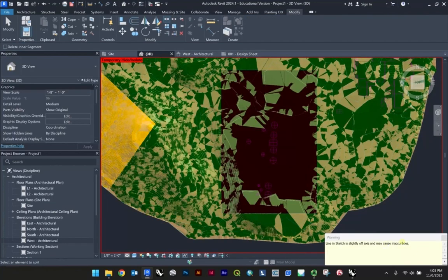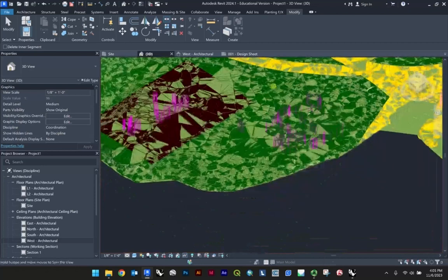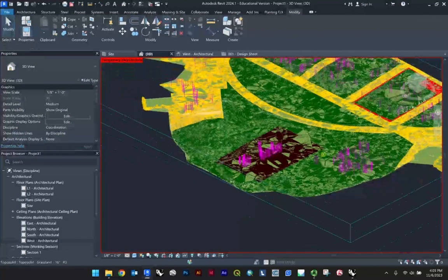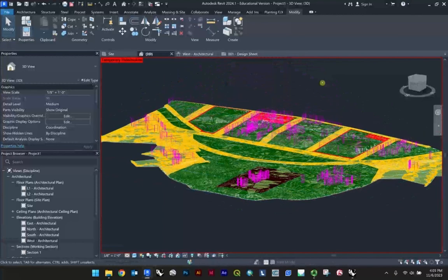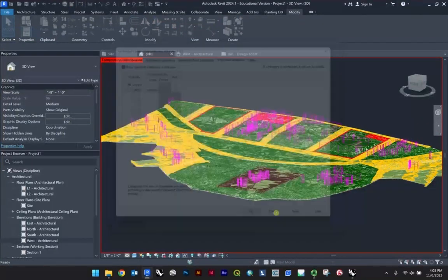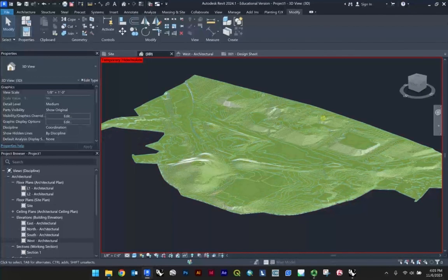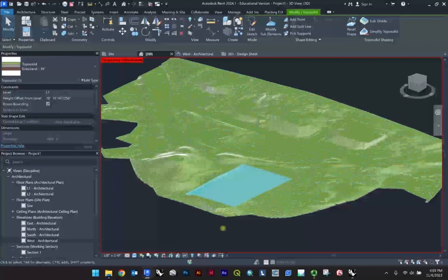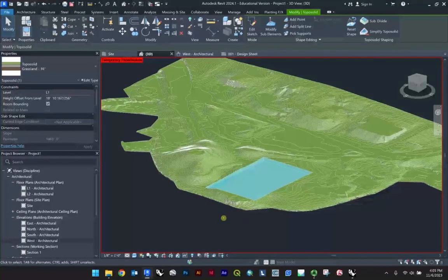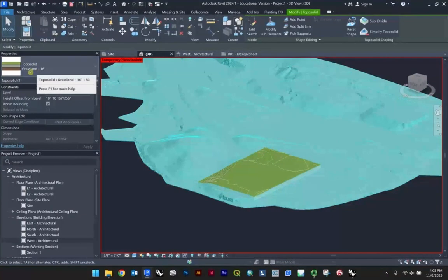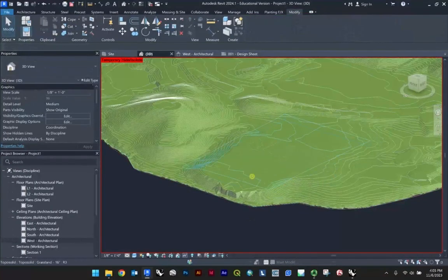Okay, so again, like I mentioned, there are seemingly always warnings and things like that. Totally fine. We're going to go back to our modify just to evaluate the work that we've been doing. I'm going to use my visual graphics and turn off this reference file that we've been using, just to show you that now we've cut out this area, right? Our site boundaries. So from a conceptual standpoint, we have a context, in this case, a topo solid that is a grassland with 16 inches of depth.